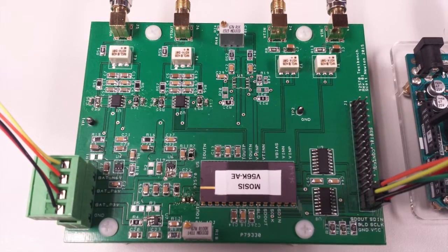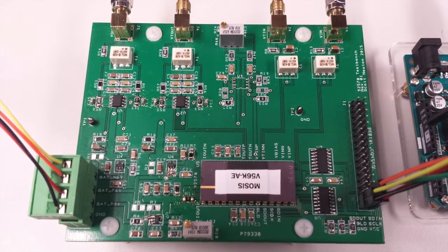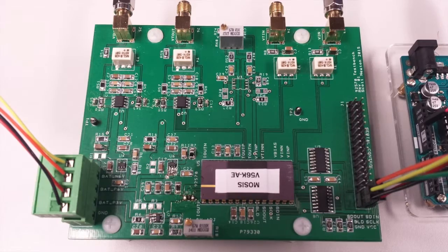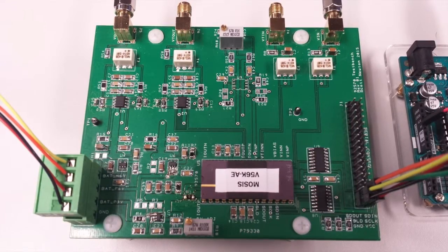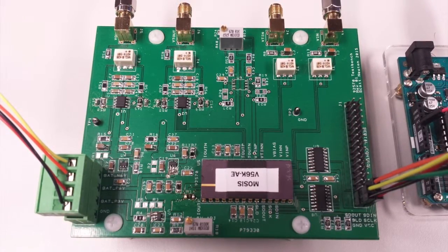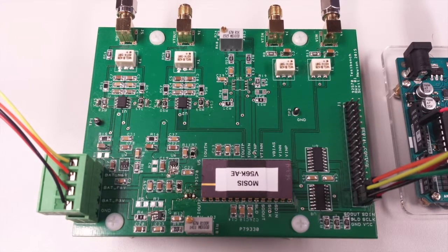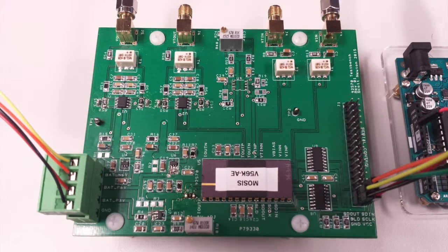The power connector is on the lower left. The signal connectors are on the top, and the serial interface connector is on the right. The serial interface supports trimming of the cutoff frequency in 11 discrete steps. My chip is the ceramic 28-pin package towards the bottom.